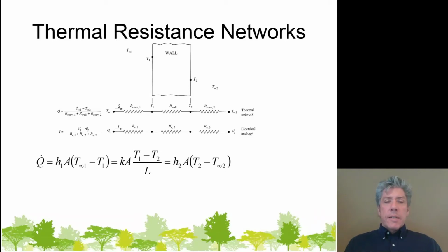Now that we have the idea that these walls and air, fluids, all these things have thermal resistance, or resistance to heat flow, and can be modeled as resistors, could we make circuits out of them? Well, yes we could. Let's make a simple circuit that's just a series circuit. Now in your electronics class you probably learned that resistors in series simply add up to one total resistance.